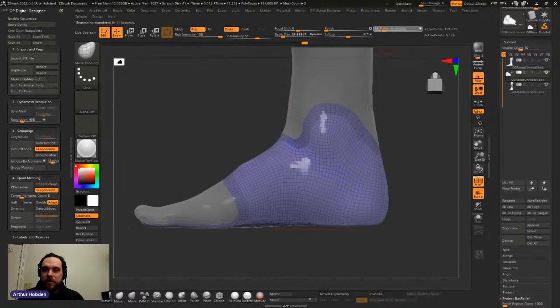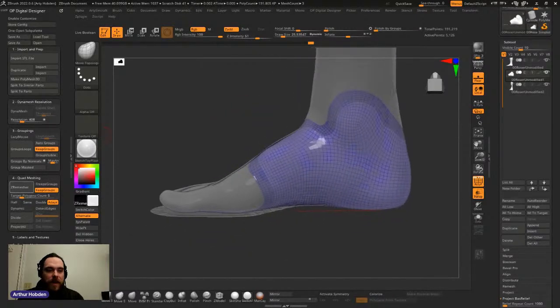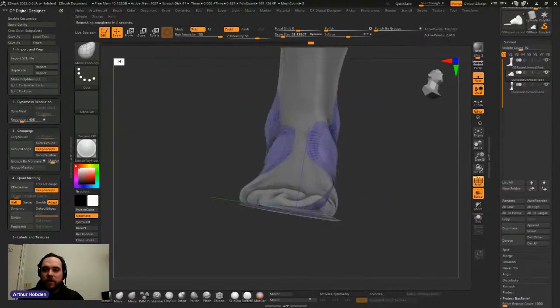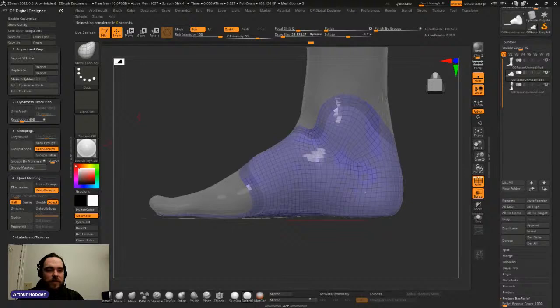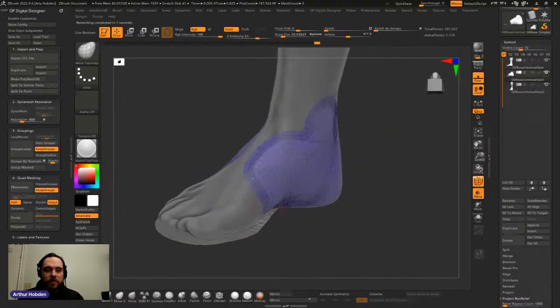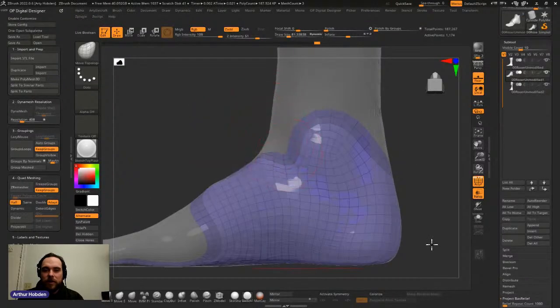We're going to polish just to get some of those trim lines to look a little nicer. We're going to half our Z measure target again and do that again. 2,000 points, not bad. I still would like it to be a little nicer. Let's try one more time at half. That actually might be a little too low. We're really starting to lose our trim line here, but I'll do my best.